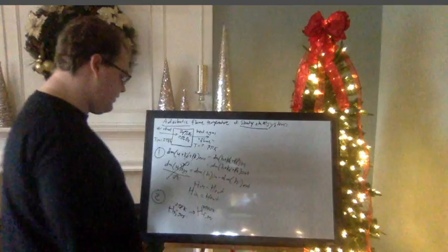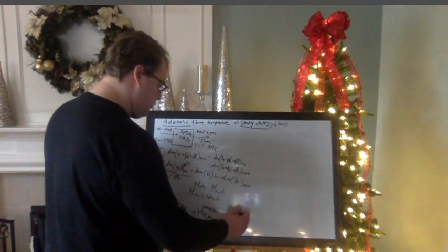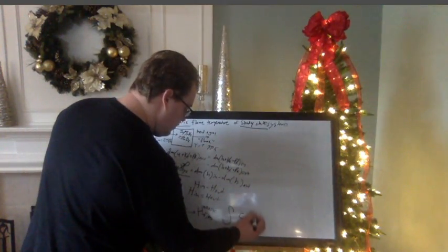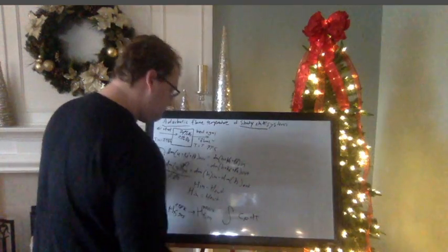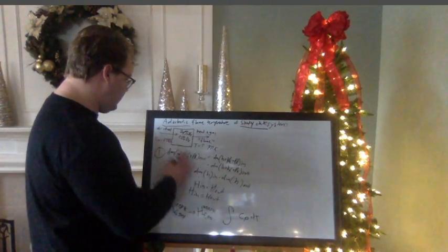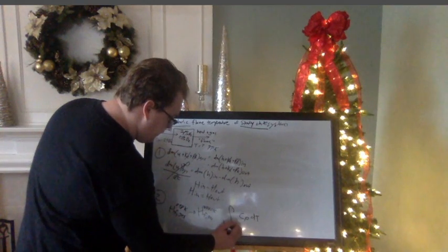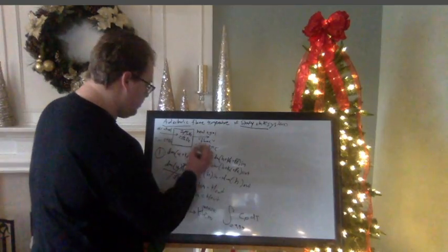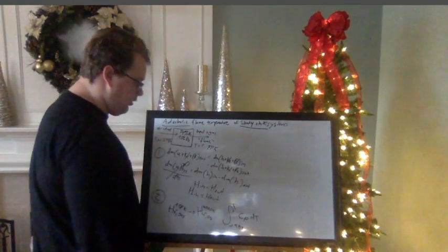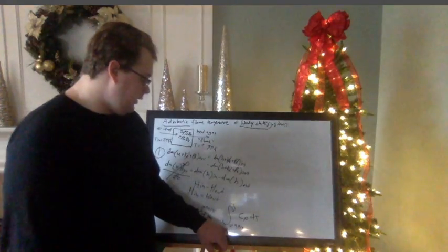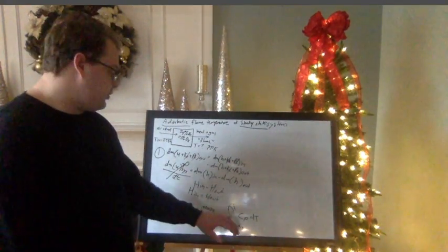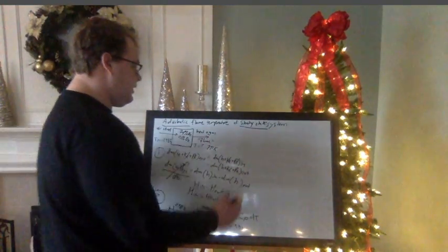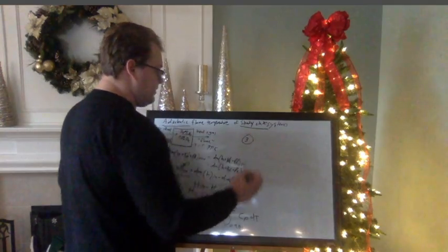In order to show this, we're going to be taking the integral of our specific heat with respect to temperature, so dT, starting at our inflow temperature of 298 degrees Kelvin, all the way to our temperature T of our outflow. So we're going to have to use this integral within some sort of specific heat equation. And the equation I'm going to be using for our specific heat is as follows.